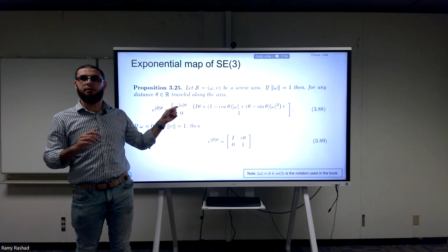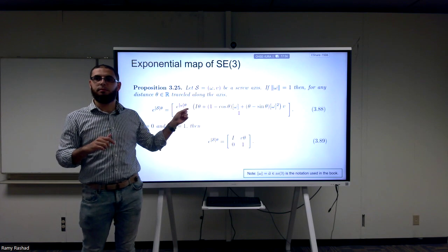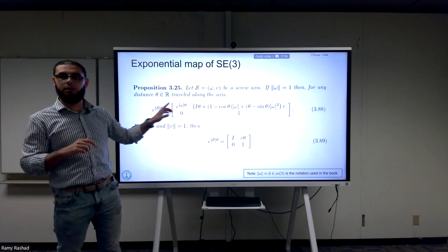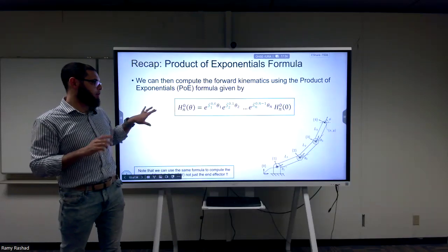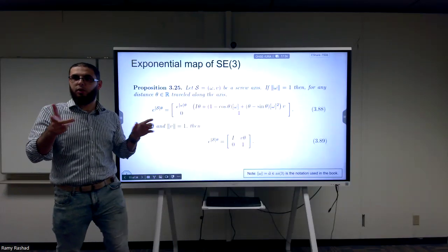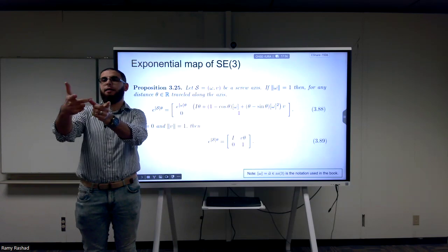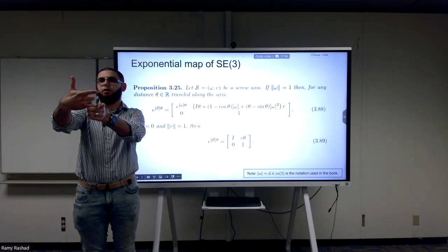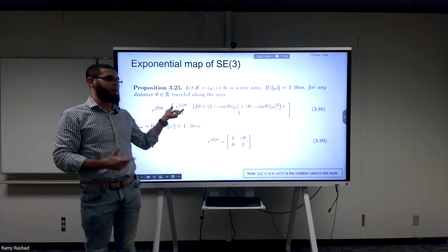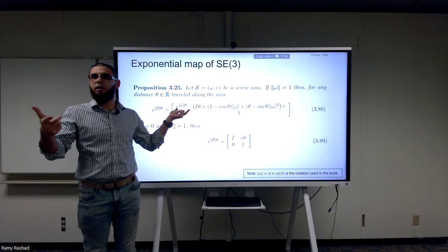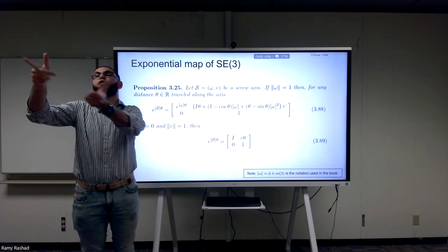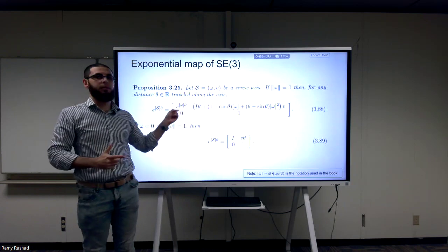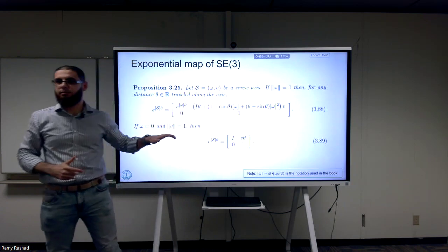Yeah, so it's a different calculation, right? This part? You mean when there is a revolute joint? Because when you have a revolute joint and you take some angle theta, you expect there will be some relative orientation, right? This new R of the body after you rotated it will be given by the Rodriguez formula. That's what this means.